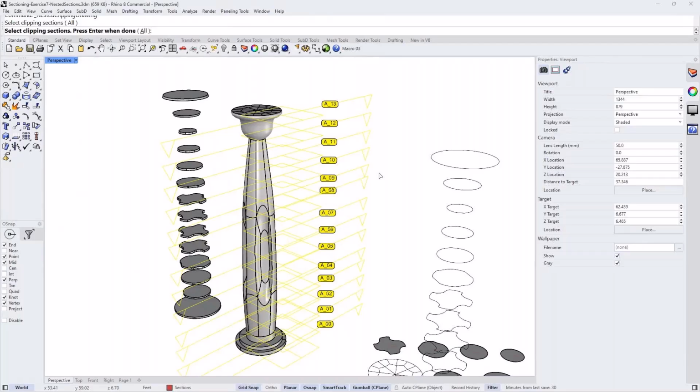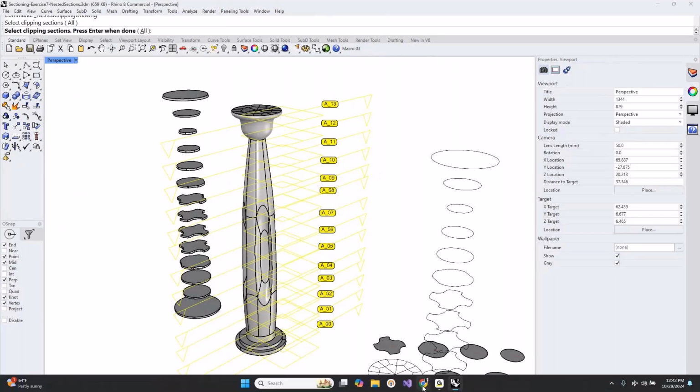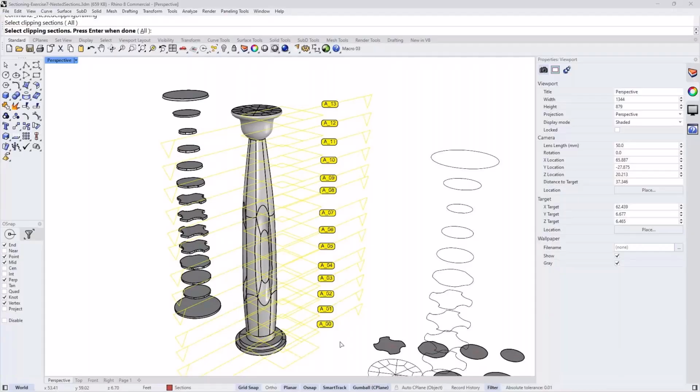I see. So your laser cutting allows you to do a tapered cut as well, you say? Well, no, you don't have that capability with a lower cost three-axis laser, or more like a 2.5 axis laser. You're going to get straight-sided slabs, and then when you stack them, you need to be able to machine down from that. Okay, that's very interesting.